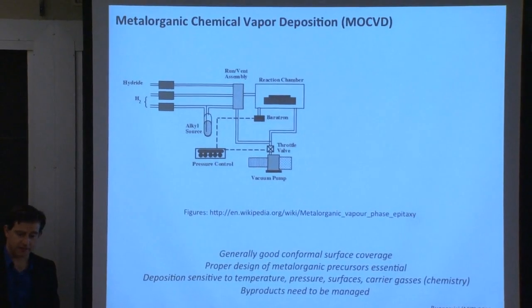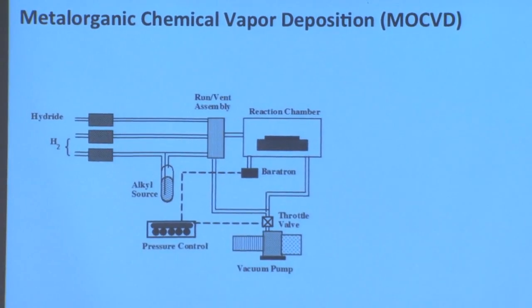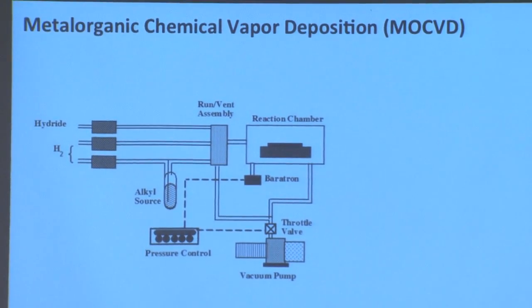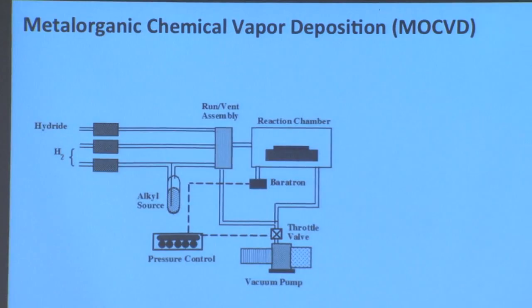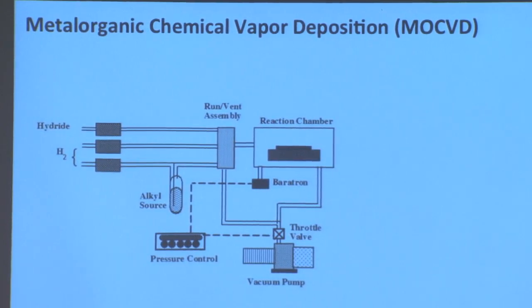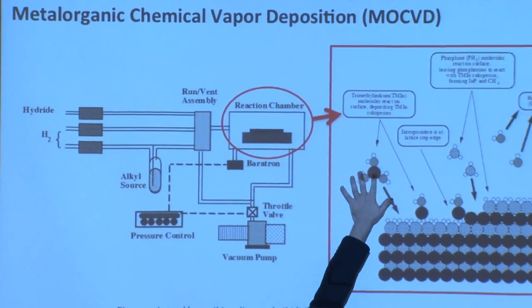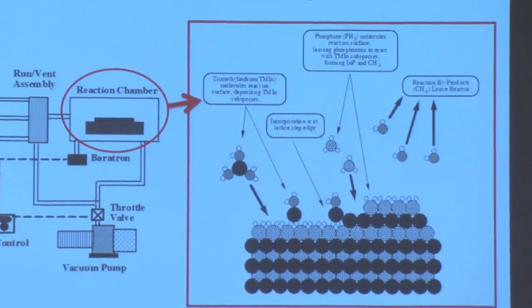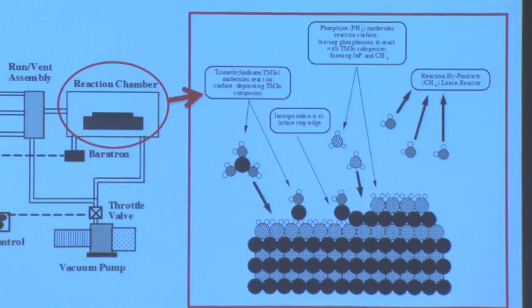Let's talk about the next technique that is commonly used in thin film, inorganic thin film deposition. This is called metal-organic chemical vapor deposition. So again, we notice the CVD appearing at the end. We know it's a chemical vapor deposition process. MO, in this case, standing for metal organic. The reason is metal organic is because we typically have a metal, like this representing the indium right here, and then little organic compounds on the outside. Those are methyl groups, the little gray and the two white dots. Those represent 3 methyl groups around the indium, so trimethylindium.